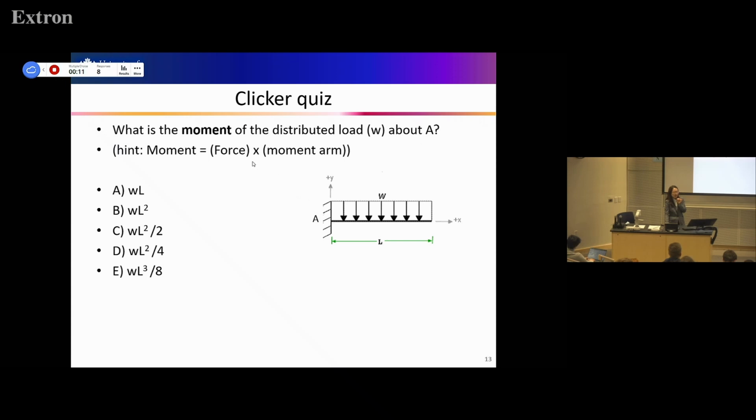And then what is the force? Resultant of this distributed load, right? So think about what is resultant from this distributed load. That's the force. And then moment arm is the distance between the reference point and the point of action, right? And where's the point of action for the distributed load?